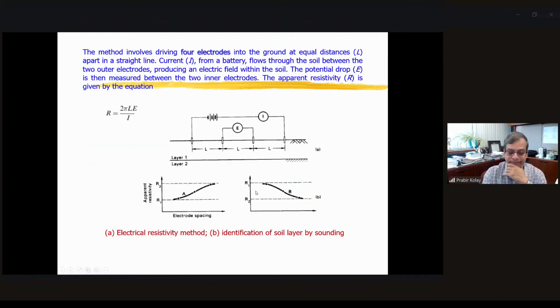All right. I know I went through this quickly, as there are so many. Basically, the borehole is the most important. You collect the soil samples using different sampling techniques and put them in a bore log with the depth, the type of sample, mostly the N value, and the location of the water table. That's the main thing. As I mentioned, this is like a blood test report.